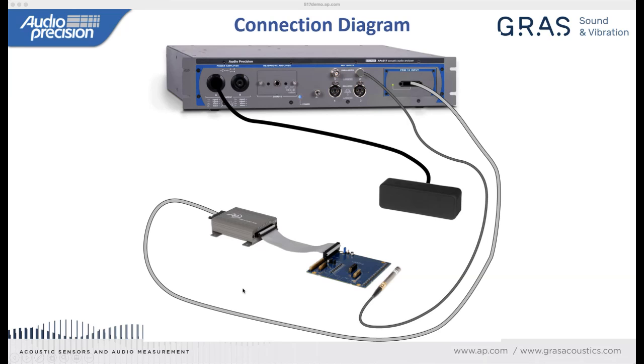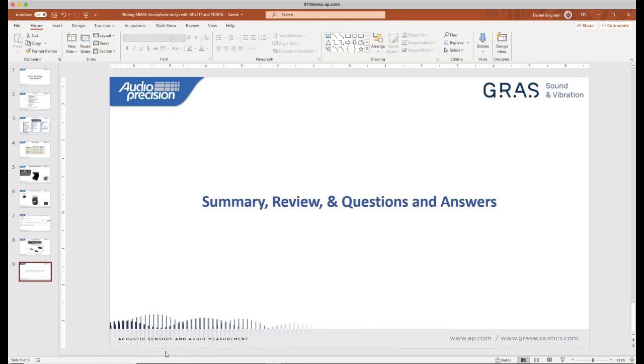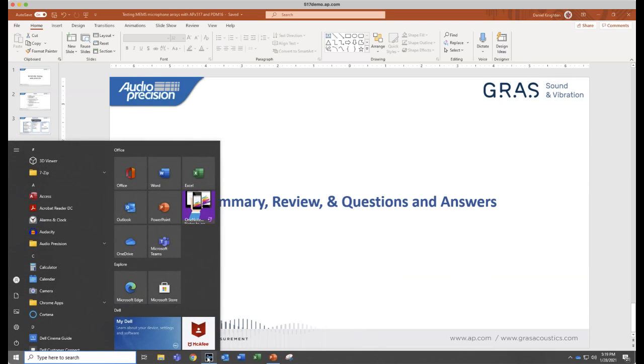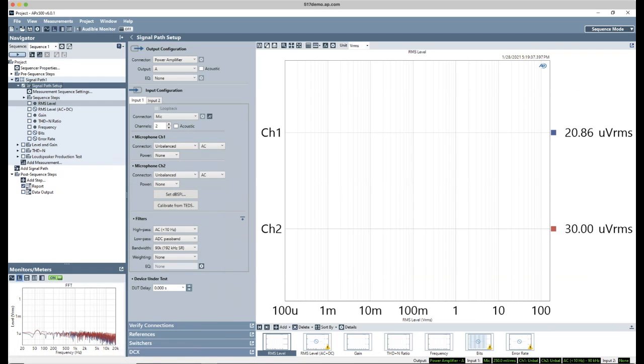And just to confirm, I am going to be testing 16 microphones today. My so-called half space measurement or tabletop demonstration definitely has some limitations as to what measurements you can make. But actually, we'll basically look at 3 fundamental measurements today: sensitivity, frequency response, and phase response. And for those 3, it actually works quite well, and I'll just show you right now.